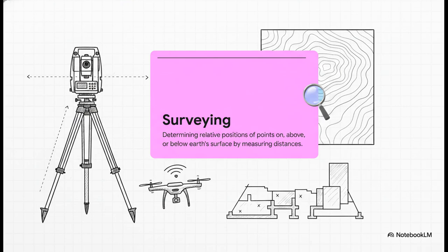However, before any of those fields can actually operate, we have to begin with surveying. Surveying is the absolute non-negotiable first step for all civil engineering projects. We use modern, highly accurate tools out in the field, like the total station, which digitally combines angle and distance measurement, alongside things like GPS and drone-based mapping. Listen, if your survey data is inaccurate, your land boundaries, your contour maps, and your entire structural layout will be drastically flawed. True safety and project economy begin right here with accurate surveying.